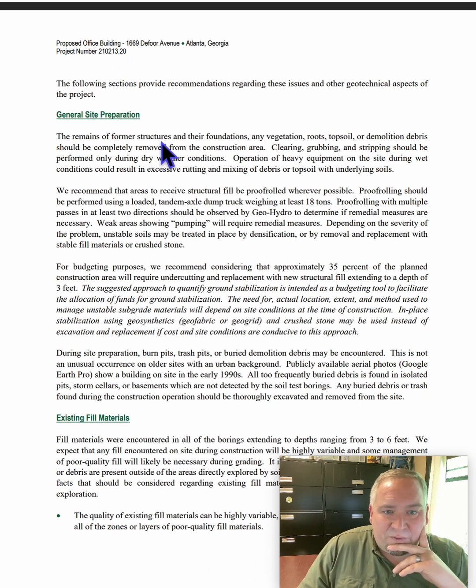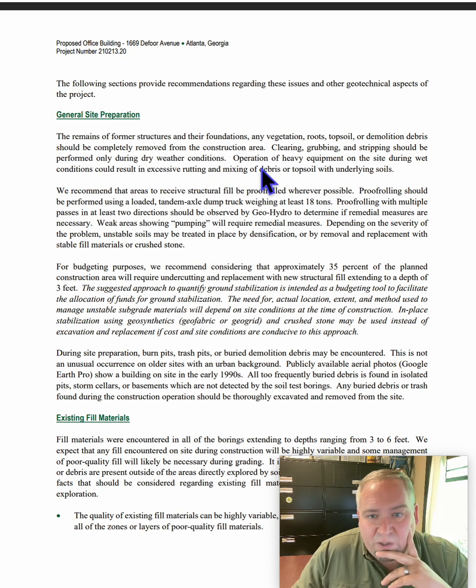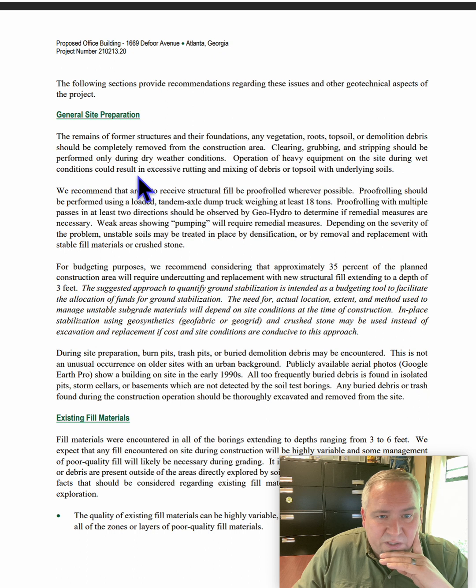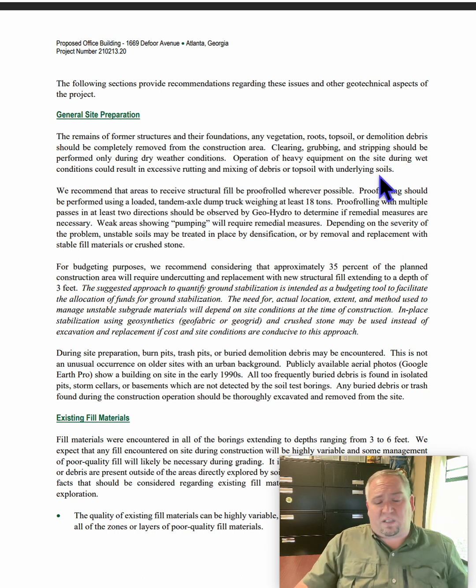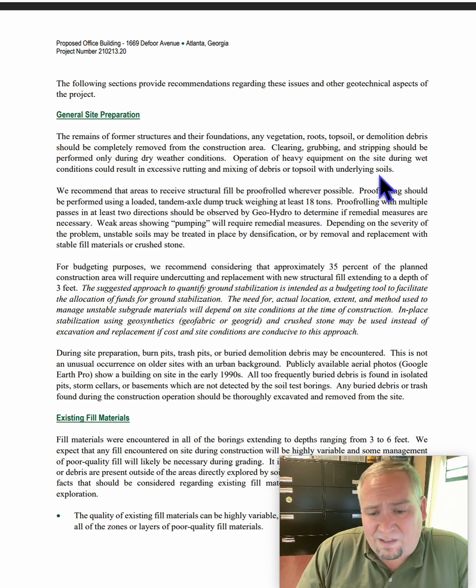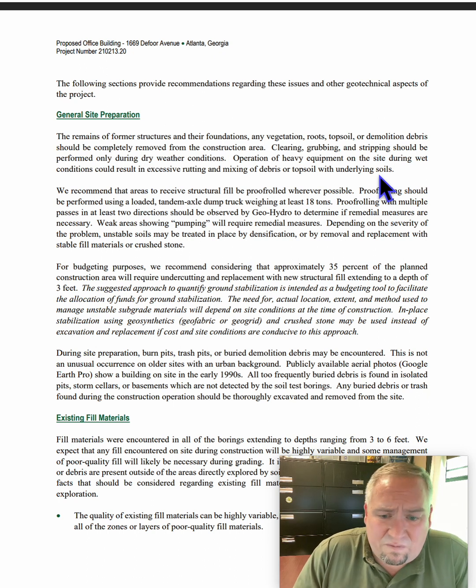So the remains of former structures and their foundations, any vegetation, roots, topsoil, and demolition debris should be completely removed from the construction area. Clearing, grubbing, and stripping should be performed only during dry weather conditions. Operation of heavy equipment on the site during wet conditions could result in excessive rutting and mixing of debris, topsoils, and underlying soil. Essentially what they're saying is, hey man, this site is likely to have a bunch of junk and other stuff. Let's not contaminate the good soil with the bad soil.